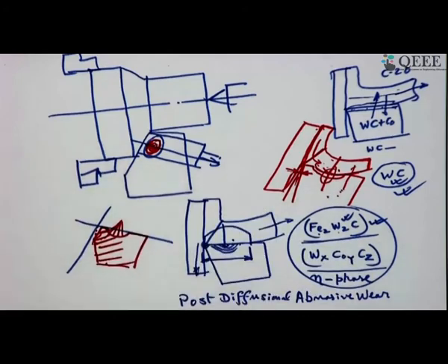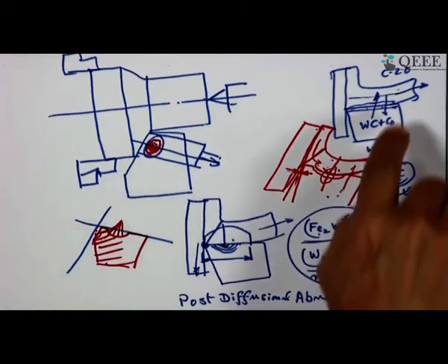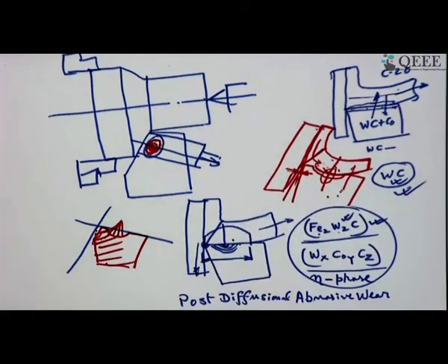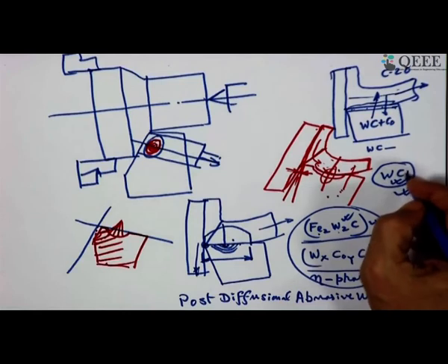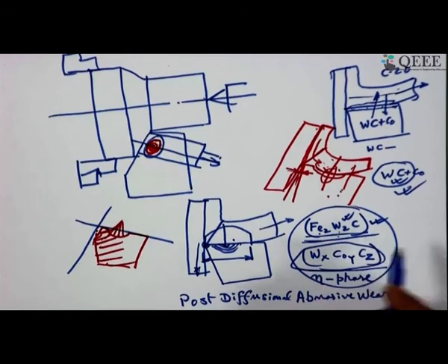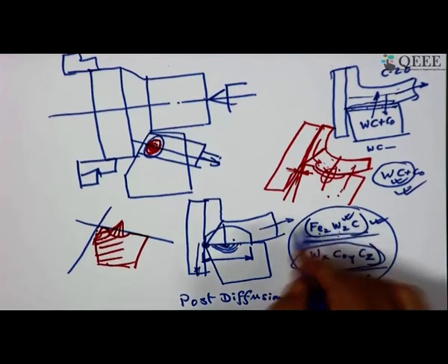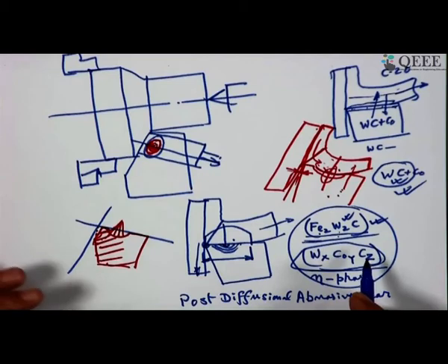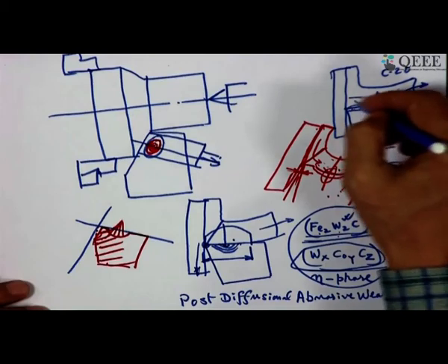As a result of that we can say in a sentence or two there is a structural change on the working surface of the rake, and this is no more tungsten carbide and cobalt. Cobalt is the matrix and tungsten carbide offers the wear resistance. It is no more this tungsten carbide and cobalt composite, rather it is this one and this is supported by this one, but this is a porous structure, number 1, it is brittle and hard. So, it cannot bear that load. It is literally washed away by this flowing chip, by abrasive action.